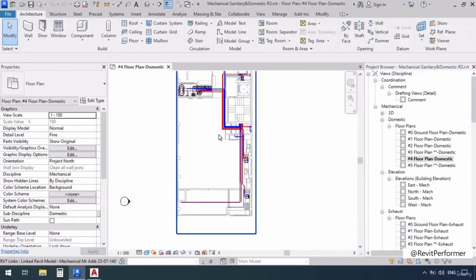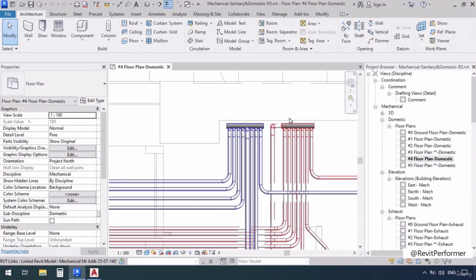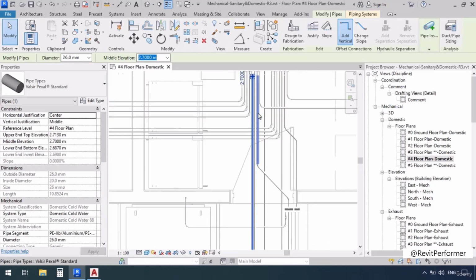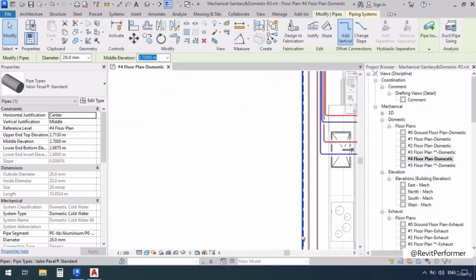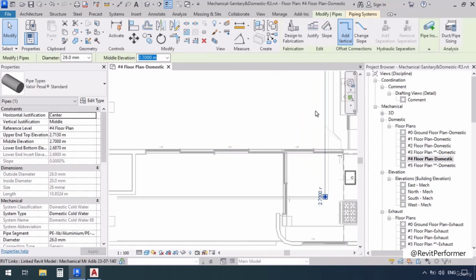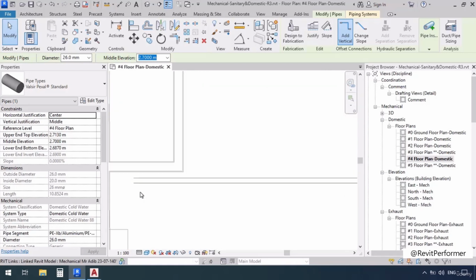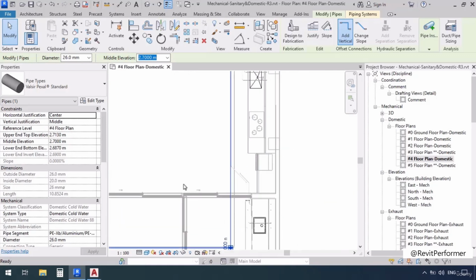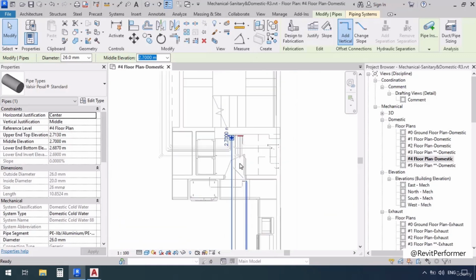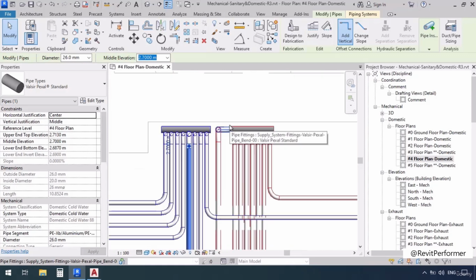Now to show you another plan type, as you can see right here in the levels, we have cold water collector and hot water collector. Some water pipes are going to come from that mechanical room and those tanks to these collectors. And then, for example, from this cold water collector, a pipe is going to come out and it comes down and continues this way. And then it leads to, based on this path, and eventually that water pipe ends at this package unit right here. In the package unit, the water is heated and then goes up this way to end at the hot water collector. As you can see, this is where the hot water enters.